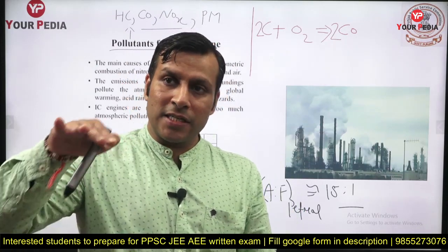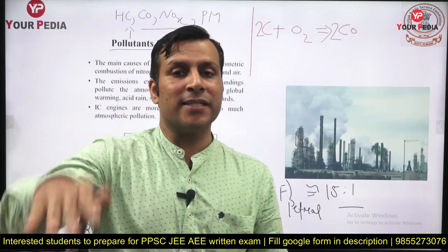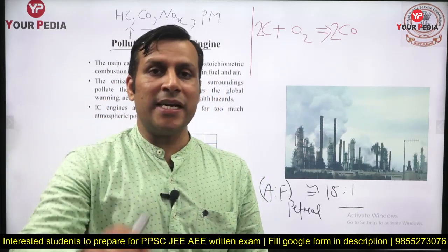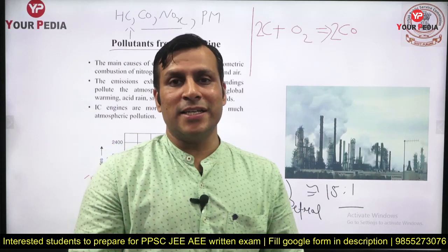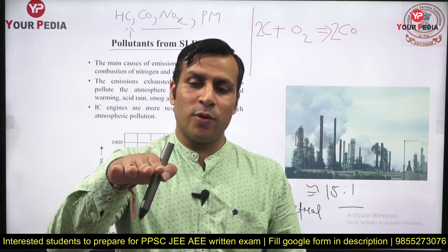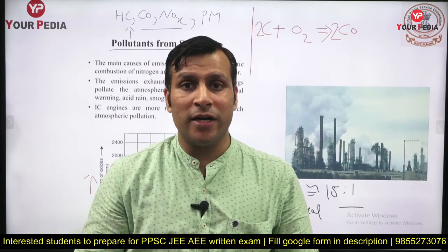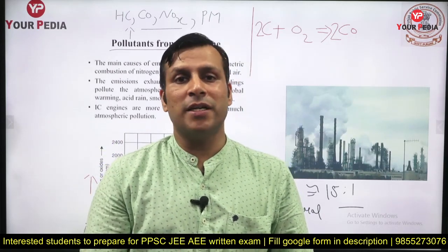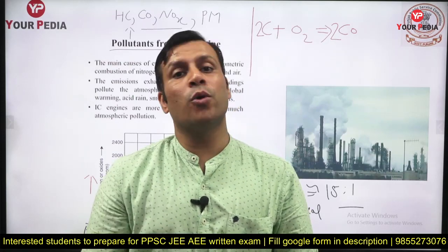Similarly, if your vehicle is standing at some light point, we generally say it is good to turn off your vehicle, and that is required. Why? Because if your petrol vehicle is standing at a light and your engine is turned on, then obviously a rich mixture is required to sustain the combustion under no load condition. So under idling, no load condition, a rich mixture is required in the engine.